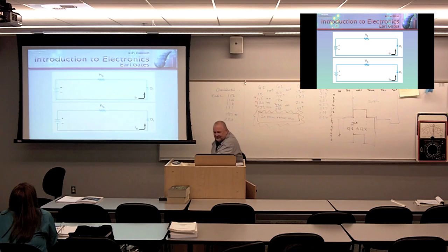If I pull this diode out and replace it with a germanium diode, what voltage will be present across the diode? 0.3, 0.2, 0.3, very good. The remainder voltage will be dropped where? Across the resistor. Okay, let's take a look at this bottom circuit.